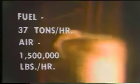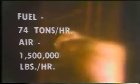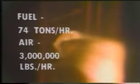The automatic control systems for fuel and air sense the decrease in steam pressure and begin adjusting the fuel flow and combustion air flow to restore steam pressure to its desired level. By the time the unit is producing 200 megawatts, the fuel flow will have doubled to 74 tons per hour, while the combustion air flow will have doubled to 3 million pounds per hour.